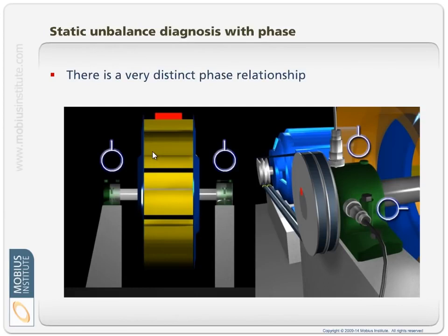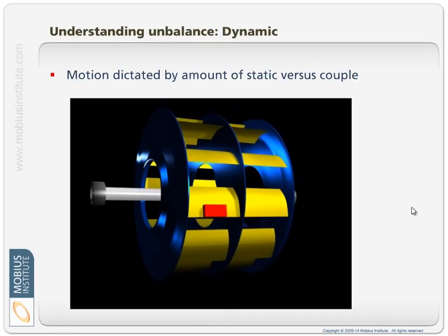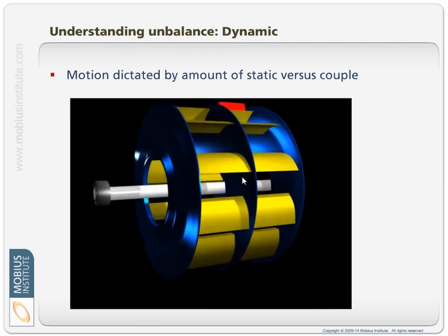How's it moving? So we come up with these little diagrams. We say, okay, the little circle and the line at the top is sort of like a reference. Rather than writing down the actual phase readings, we just draw it this way. So because the little line's going up in both cases, that means it's in phase. Because one's going at 12 o'clock and one's at 3 o'clock, that means there's a 90 degrees phase change, and it confirms unbalance. Here we've got, call it dynamic unbalance.